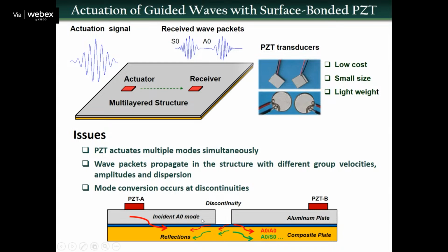In this case, which is shown here, they can be sensed using the same type of sensor, and then we can do data processing. The advantage is very obvious: you can make very low cost and small size sensors. It can be PZT, PVDF, and so on. You can actually cut those sensors into small patches and attach them to the structure.